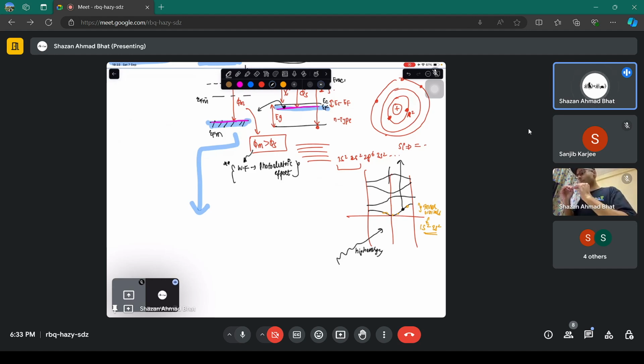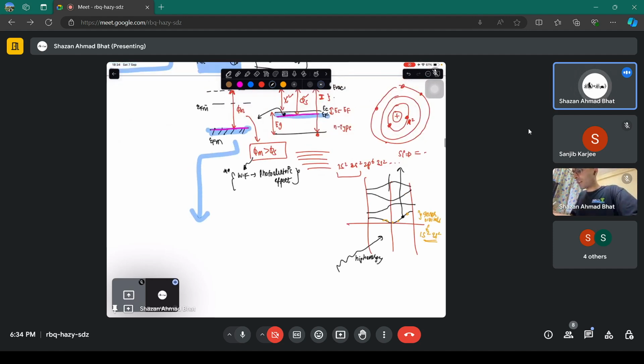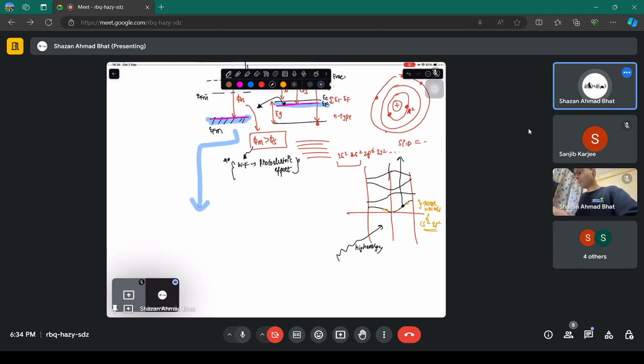Up to the point the Fermi level is flat for the system, because now you're combining two different systems. When they were separate systems, they had different Fermi levels. Whenever you have a single system, it has to have a single Fermi level. It cannot have two different Fermi levels. In some non-equilibrium circumstances it can, but under equilibrium, it cannot. So whenever it does so, the electrons go from this region towards the metallic region.